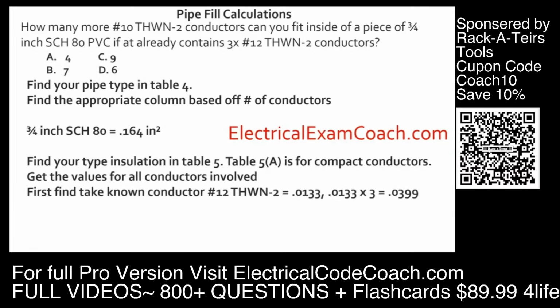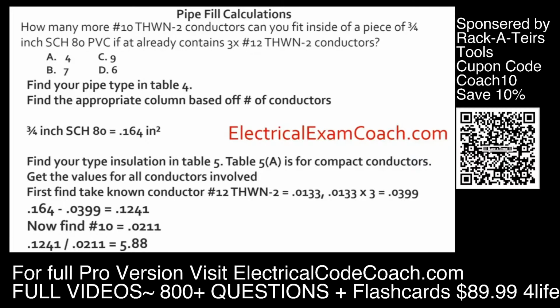First, we're going to take our number 12 that we already have, multiply it by the 3 that we already have, and that gives us this value. Then we're going to take our total available to fill, minus what we already have, and that gives us this for our remaining left to fill. Then we just take that and divide. We divide that out and we find that we can fit 5.88 conductors, and in this case it is 0.8 or larger, and we will round up to 6.